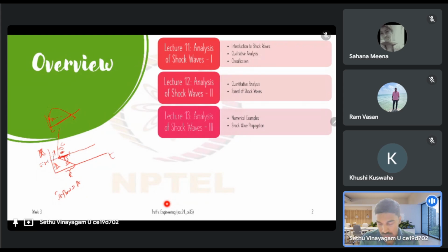So what happens once the red time finishes? You have green time starting again. What happens at green time? You will have flow at capacity, or at the saturation flow rate. Why? Because you have enough demand that has accumulated during the red period, and once the green time starts, all these vehicles will be leaving at capacity condition, right? Let us say that is D.